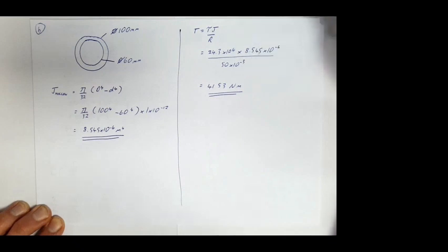Okay, so the amount of torque that the shaft can carry for the same stress has gone down slightly because the J value has gone down slightly because we bored it out. So the second part of the question then says, what was the percentage increase in the power to weight ratio effected by this modification? So let's now have a think about that.